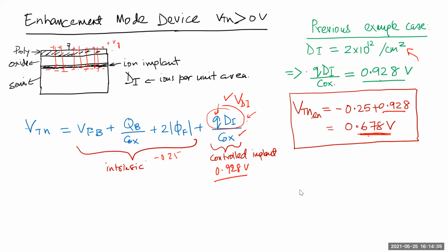Actually, it depends on which SiO2 you're asking about. Just saying SiO2 is not complete, in the sense that SiO2 is also used as a mask, but it is also the insulating layer before you start doing the metallization. So if you're asking whether we do it before the metallization, yes. But the SiO2 is also used as a mask for doing the ion implantation.